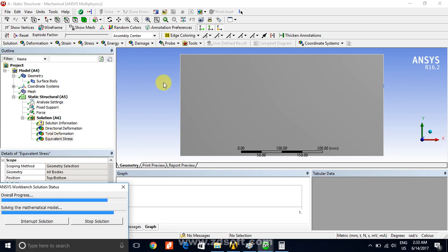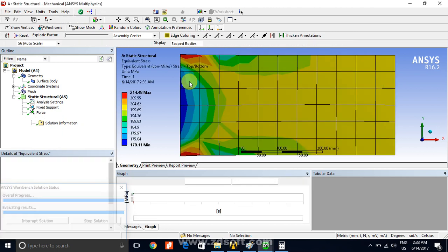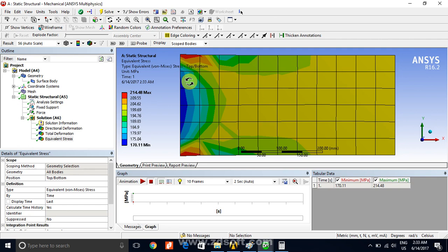In this case, because this is a uniaxial loading condition, sigma 1, sigma 2, sigma 3 in the von Mises stress are the principal stresses. You know what the principal stress is. These principal stresses are developed in the principal plane. Actually it is the normal stress, where normal means normal to that plane in which the shear stress is 0.